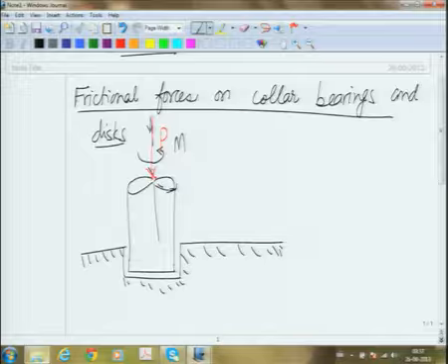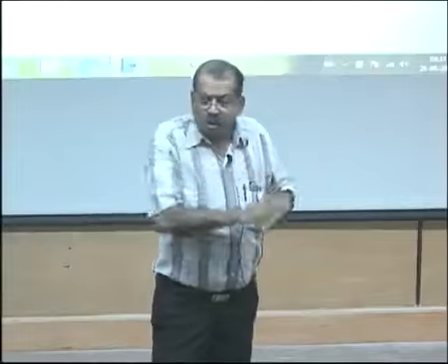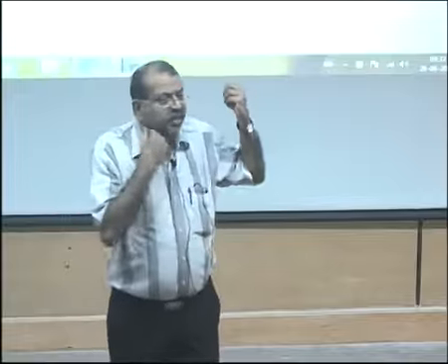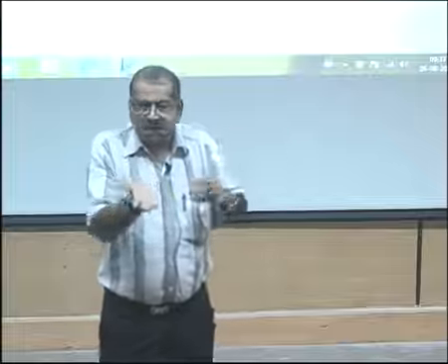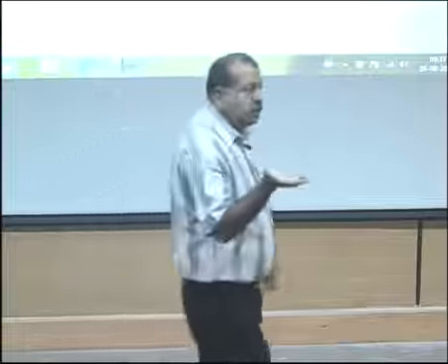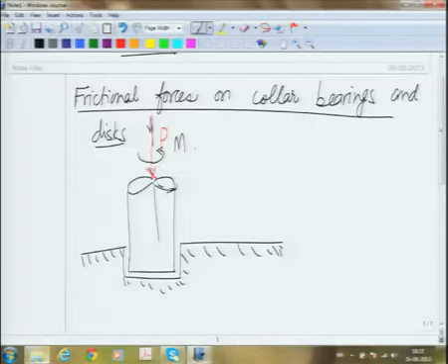This is what we will call the frictional moment: how much moment has to be applied to overcome the moment because of friction. And as I will show you, in a contact like this, friction does not cause a net force on the body. It causes a force, but then an opposite force comes from the other side. So, the net effect of friction will be in the form of a couple. So, this could be one type of contact.